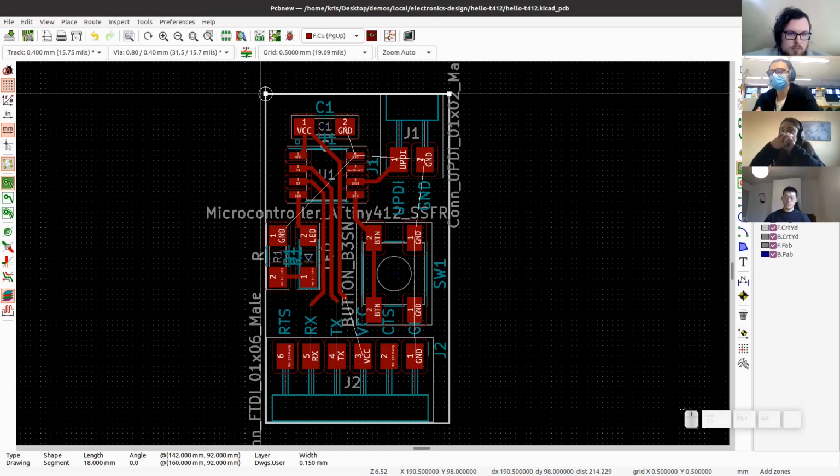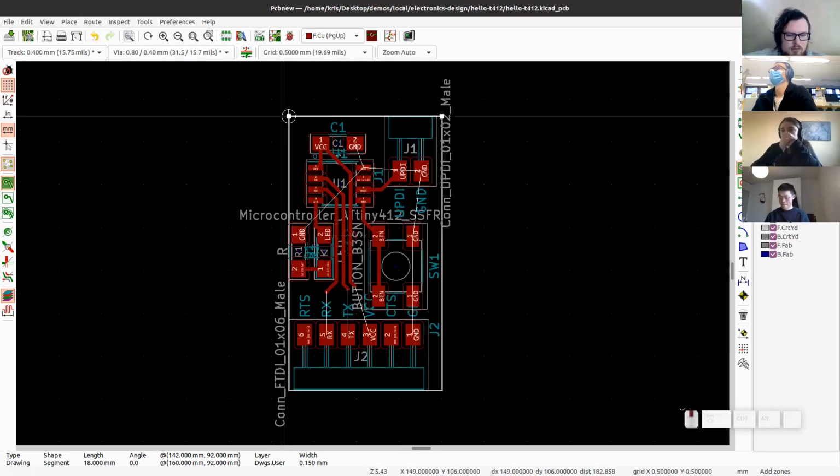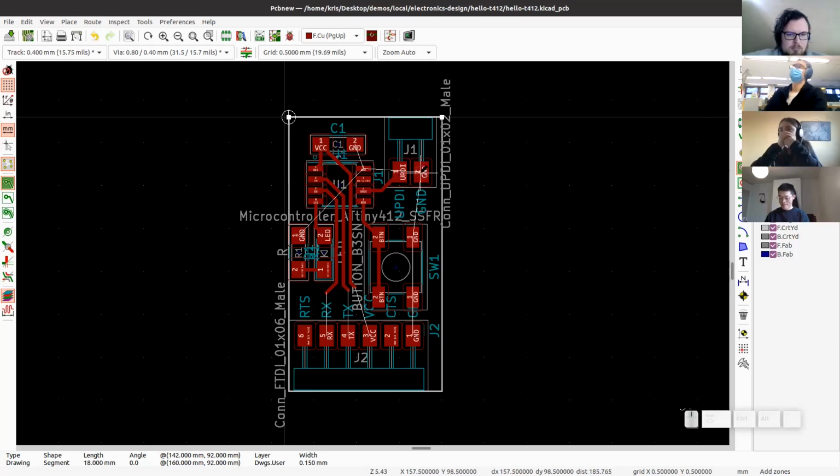More like that's kind of a hack in order to make these boards fabbable, so to say. Then there are edge cuts, these eco layers. I'm not sure what these are, but we're going to use only the front copper and drawings user layers, and also the margin layer in your designs. But yeah, in order to create these copper fills, we need to select the front copper layer.